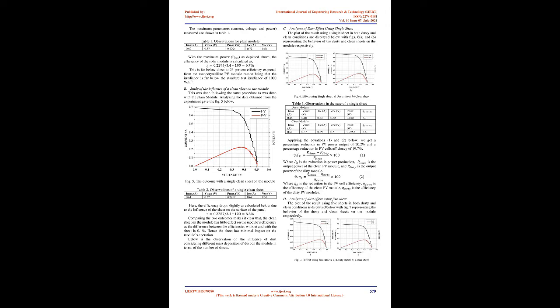on a clear day. A variable resistor is used as the load to the solar cells, with the resistance being varied and measuring the voltage and the current produced by the solar cells unit. The load resistance characteristic values are 100 ohms and 2 W maximum. The complete setup of the solar kit used in this experiment is shown in Figure 1.